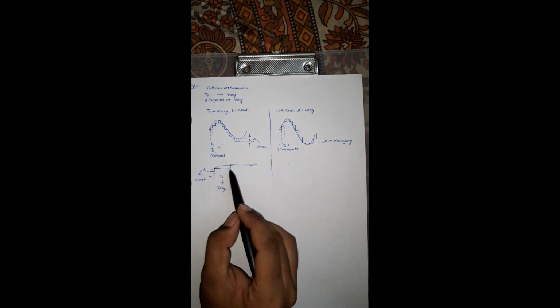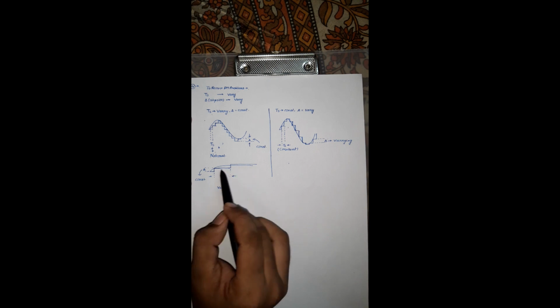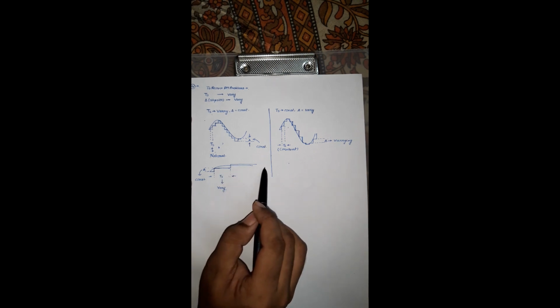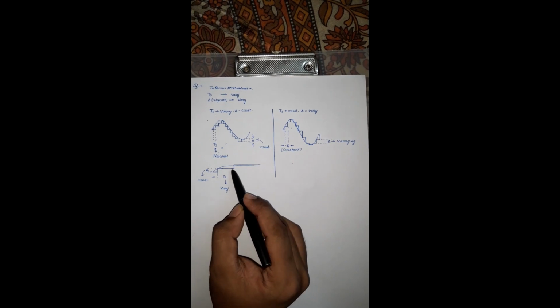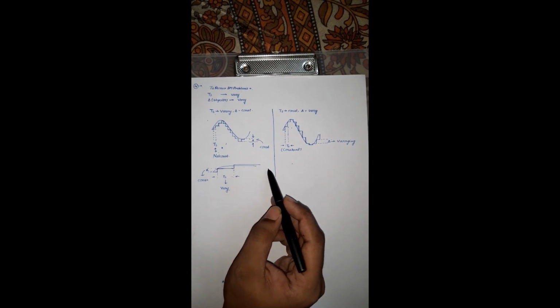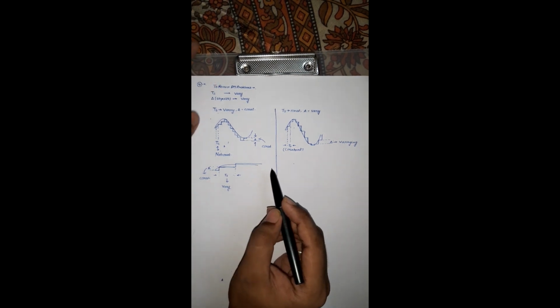If we notice a constant value at the present step, at the present sample instance, and it detects that after this sample instance the signal is not changing too much, or has a constant value, then it will drastically increase its TS, or the sampling time interval, so that the value after sampling remains constant, or it can follow the input waveform.